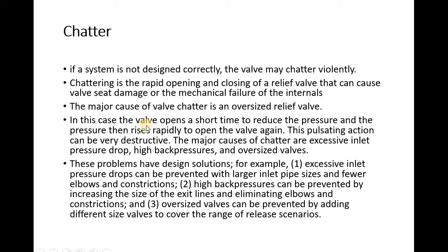And what do you mean by oversizing? Actually, this is what it means here. It's written, the valve opens for a short time to reduce the pressure. So you oversize it. That means with a very high pressure, it started opening, and actually it should have opened before. So now when you reduce the pressure and it closes, and then it goes up again. Why? Because you did not let off the pressure enough. And the pressure then rises rapidly to open the valve again. This pulsating action can be destructive.